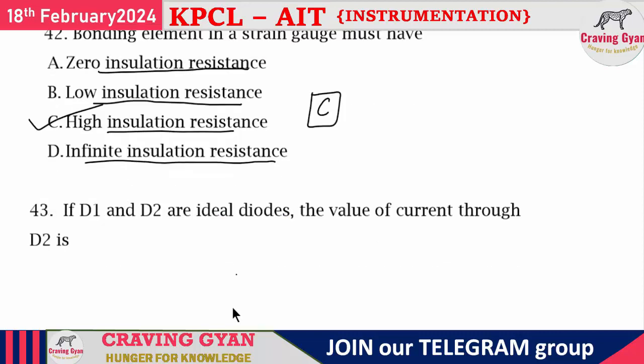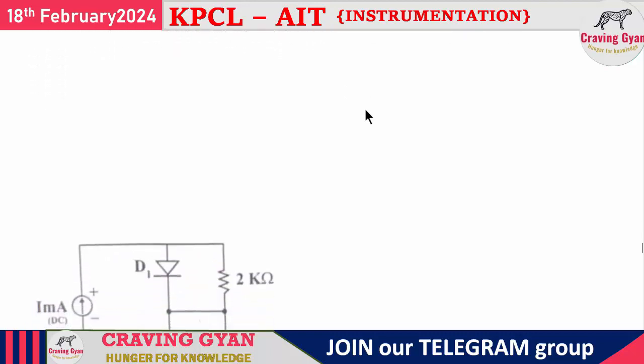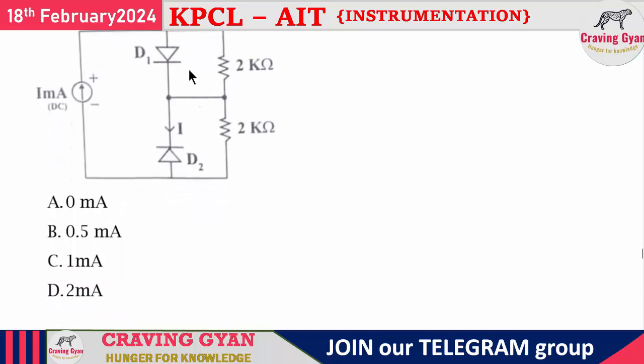So now onwards we can slightly focus on the problematic questions also. 43rd question, if D1 and D2 diodes are ideal ones, then the value of the current through D2 is. Now look at the things. Among D1 and D2, which is forward biased, or which one is conducting? The anode terminal of D1 is connected to the positive side of the current source. Here in the case of D2, the anode is connected to negative.